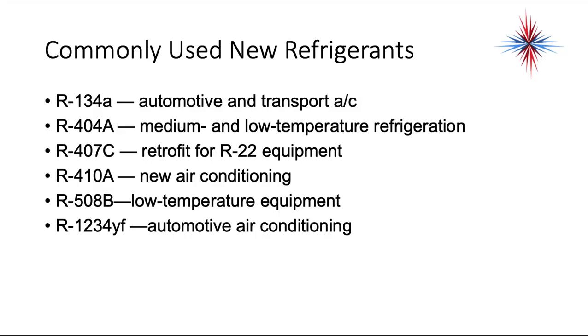Commonly used new refrigerants, these are the ones that are going to be around. R134A is used in automotive and transport. R404A, medium and low temperature refrigeration. R407C, it's a retrofit for R22 equipment. R410A, new air conditioning. R508B, low temperature equipment. R1234YF, automotive air conditioning.